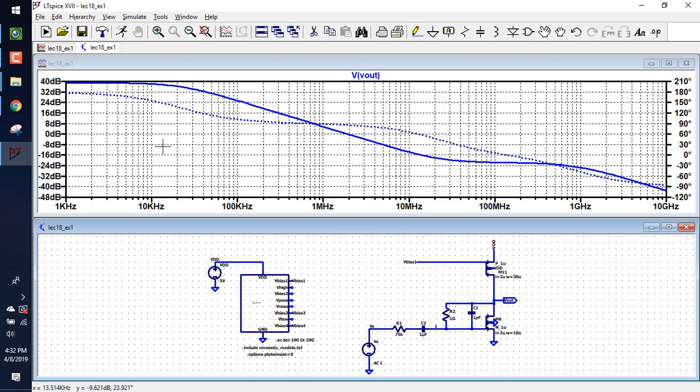Let's look at the phase shift. I've got a pole here. Notice the phase. We got 180 degree phase, which means the amplifier at low frequencies. What does that mean? 180 degree phase at low frequencies. What's that? Yeah, it's inverting. Then that pole causes, at roughly 20 kilohertz or whatever, the phase to start rolling off.